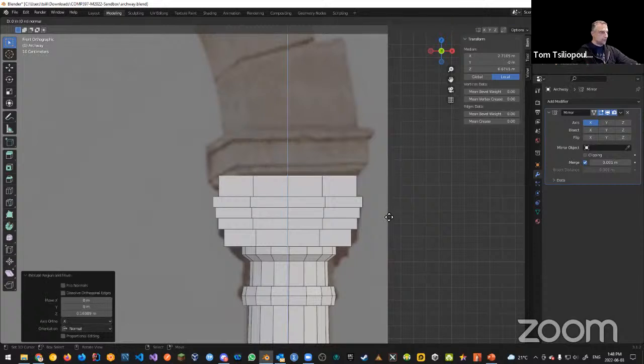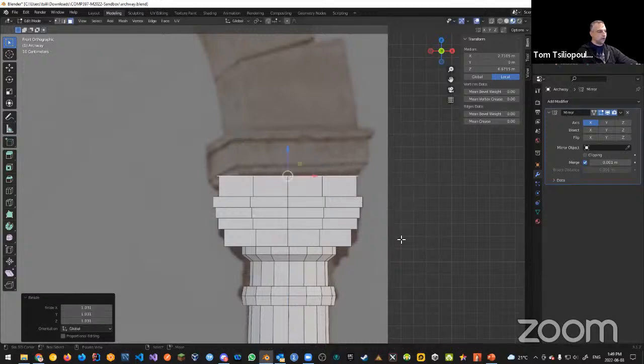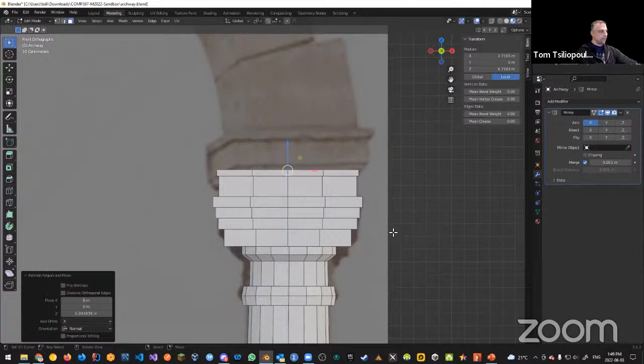Okay, and then extrude, enter, scale, where we have that extra geometry. And now we're going to extrude up just to that lip. And we can start to turn it. And the way to do this is to rotate it, R across the Y-axis, so that we can kind of start turning the object a little bit up this way.